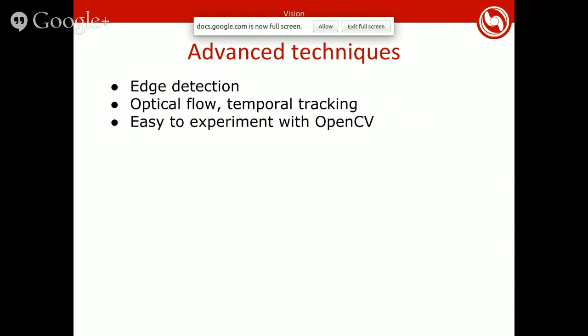And what we really need is if you could give hints to this algorithm based on what your vehicle is doing. So characterizing your camera and saying, okay, if I'm strafing and I'm rotating in this way, the objects in my image are going to move in this fashion. Potentially you can have some Bayesian model that takes in your velocities and the image output and says, okay, if I'm moving at this rate and the object is here in my image, the most likely position for it in the next frame is going to be here. And this is going to be related to the physics of your camera, your field of view, your camera distortion parameters, and so on and so forth.